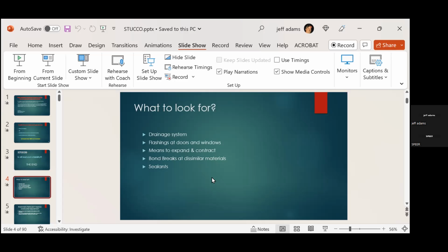You start buttering them up to the aluminum windows, it occasionally will just eat away at those windows. You're going to see here in the code that aluminum head flashings are not allowed to be used, but yet we're buttering plaster cementitious products straight to the aluminum windows, and it does create an issue from time to time. Why it does it in one area, not the other, I don't know, but you will down the road see windows completely eaten out from the cement.